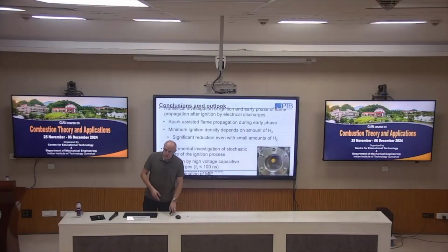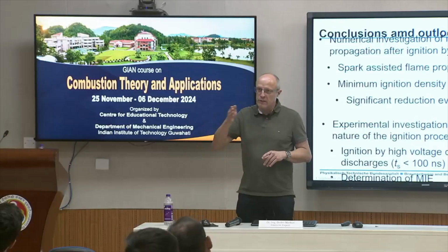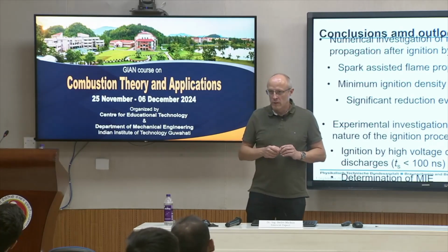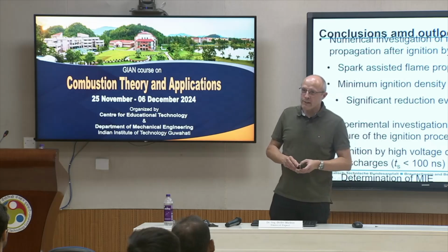So one possibility is to use a pipe and adjust the inflow velocity so that you have a stable flame position. Then the velocity of the unburned gas mixture is your laminar burning velocity. But of course, this is quite complex.